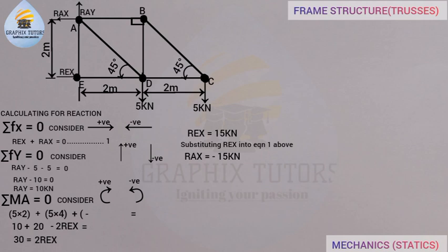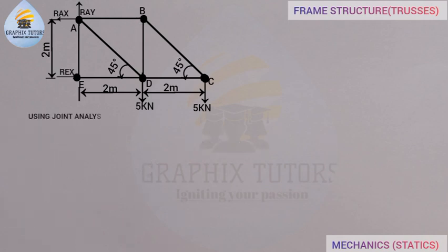Now, when I mean the force acting along each member, it is this. If you look at member AB, there will be forces acting at it. So I'll call it this way. This will give me FAB and this will give us FBA. Remember that FAB is equal to FBA, right? There's a force acting there. Similarly, along member AE, there will be a force acting in this direction here. This will give my FAE and my FEA. They are both the same.